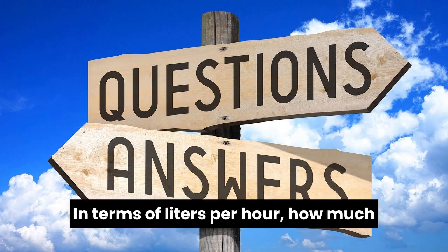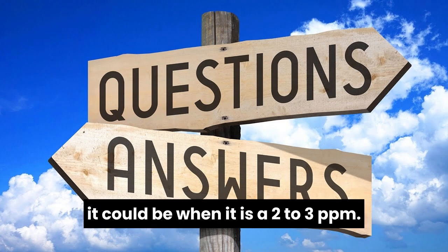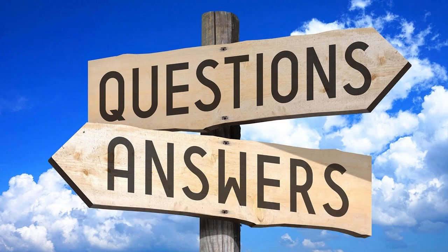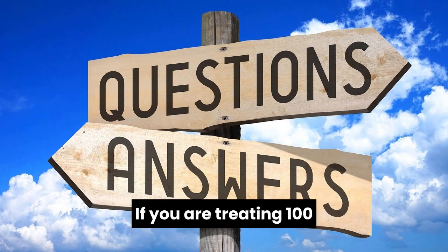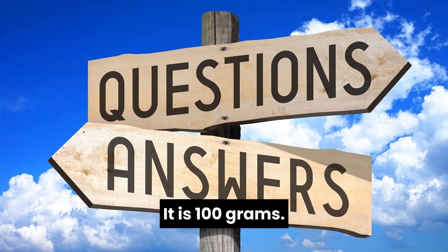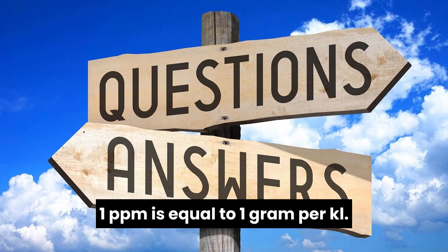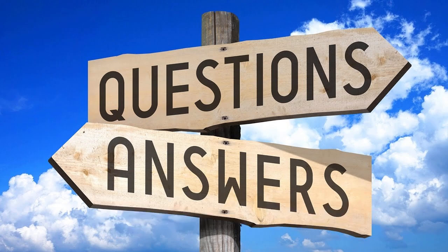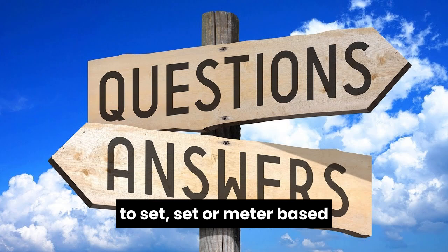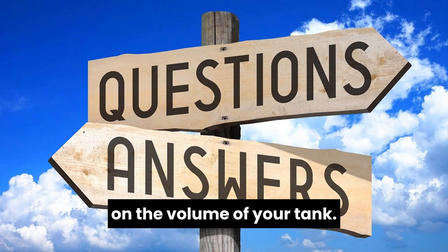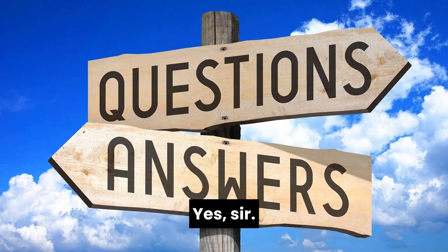In terms of liters per hour, how much could it be when it is 2 to 3 ppm? See, 1 ppm means 1 gram per KL. If you are treating 100 KL, it is 100 grams. 1 ppm is equal to 1 gram per KL. So accordingly, we have to set our meter, based on the volume of your tank.